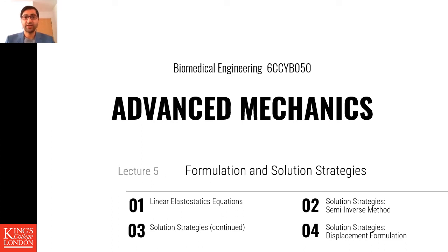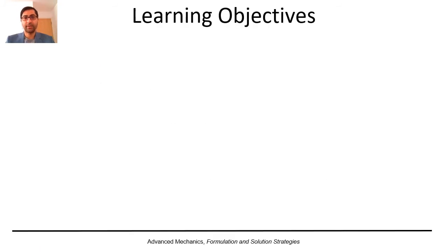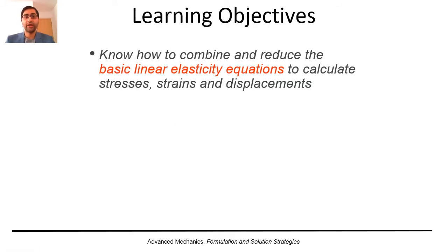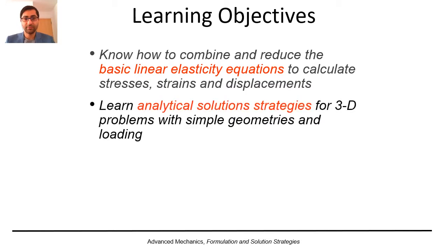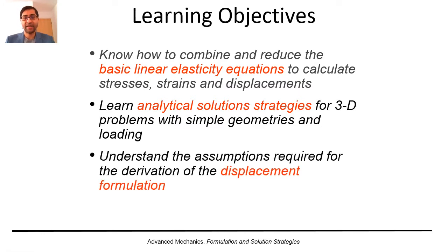Today we're going to see how what we've already learned in the past few lectures can be implemented in some practical examples. We're going to talk about formulation and solution strategies. Learning objectives are knowing how to combine and reduce the basic linear elasticity equations, learning analytical solution strategies for 3D problems with simple geometries, and understanding the assumptions required for derivation of the displacement formulation.